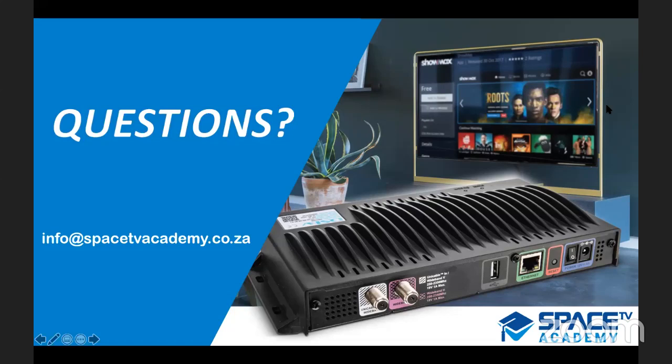I've got Fred here. Thank you for your presentation. My question is, do I need more than one wideband LNB if I am to use more than one server? If you have a wideband LNB, you are able to build a distribution system behind it. In other words, you can split them. There are wideband amplifiers available. There are wideband taps and splitters available.